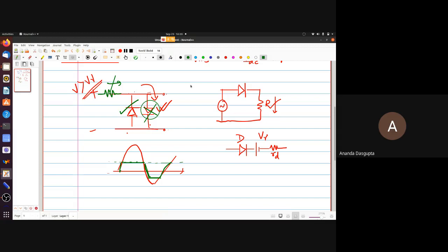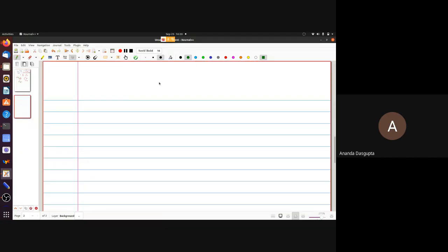Of course, instead of this bias which is there because of V gamma, you can also put in actual voltages, batteries to bias things, right? If you do that, then if you put a diode here and put an opposing voltage, let's say of 2 volts here, then this diode will only conduct if the input goes beyond 2.7 volts. I'm assuming cut-in voltage is 0.7 volts. And so once the input goes beyond plus 2.7 volts, maybe up here,